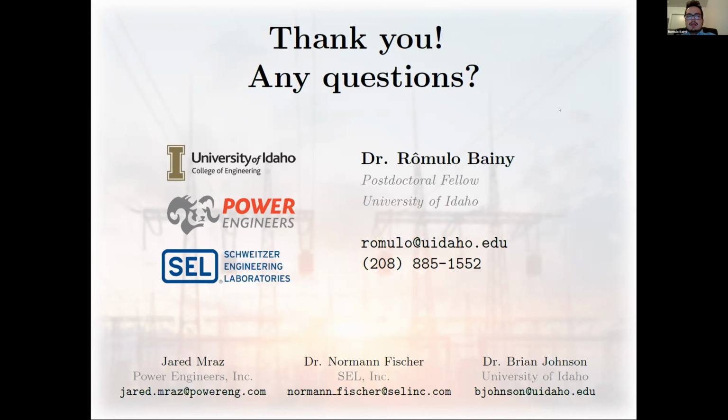So these are basically two questions. The first one, how much of the grid was included in the analysis? In this case, we were focusing on the series compensated line, so we included all the details. In these studies, we didn't include the protection schemes of the capacitor banks, for example, but we included the whole model of the line, shunt reactors, and the series compensation, the series capacitors.